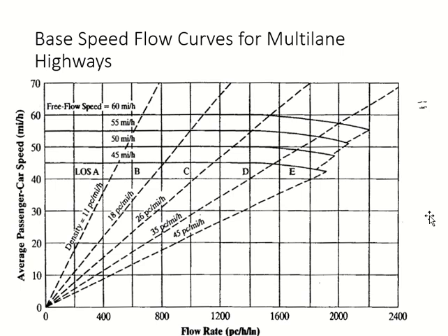But the important point is we cannot use these curves unless I have the same type of highway and the same speed. You cannot use this curve for a 2-lane highway, or for a multi-lane highway which has a speed of 51 or 52. There's no interpolation, there's no average. Your speed should be 50, 55, 60, 45, the values shown in the graph. Then you can use the curve to find your level of service and the service flow rates. But all these things are restricted. So this is it, and then we'll continue next time, inshallah.